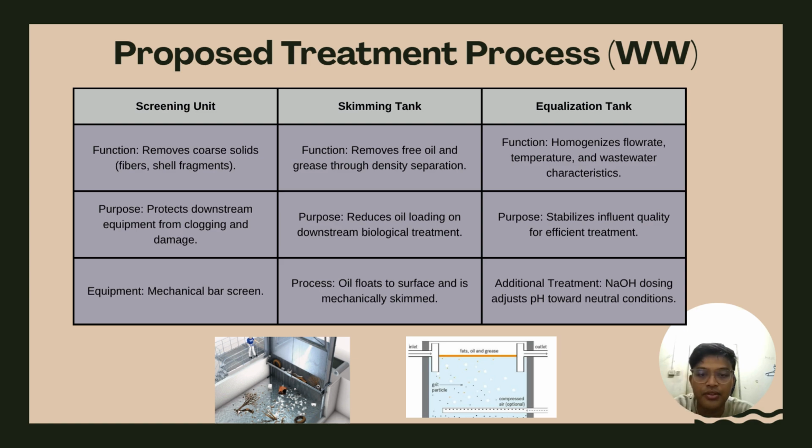Assalamualaikum warahmatullahi wabarakatuh. My name is Muhammad Ashraf bin Umar Amin. Now I will talk about the proposed treatment process. These are the preliminary units proposed for the POME treatment system. First, a screening unit is proposed to remove large solids such as palm fiber and shell fragments. This helps prevent clogging and protect downstream equipment.